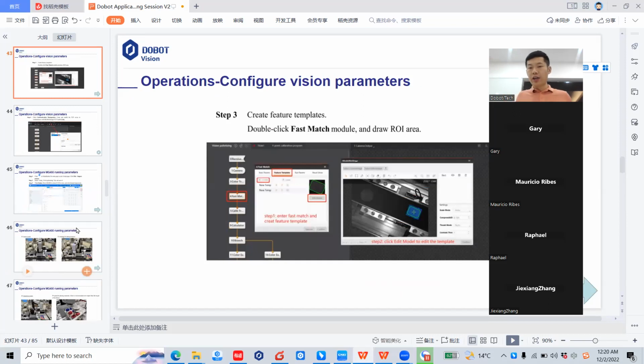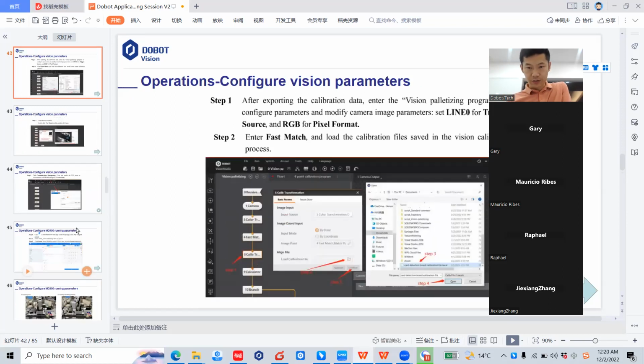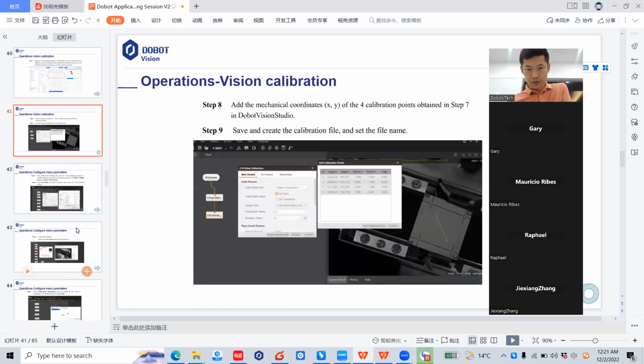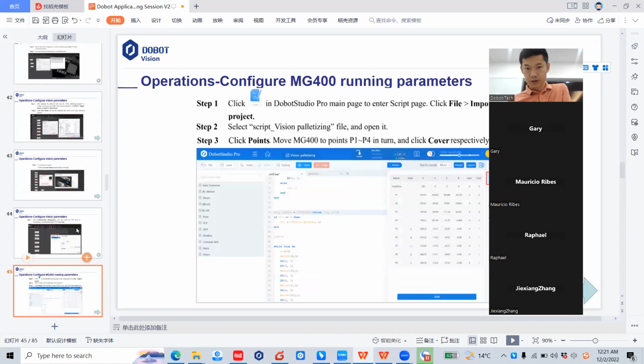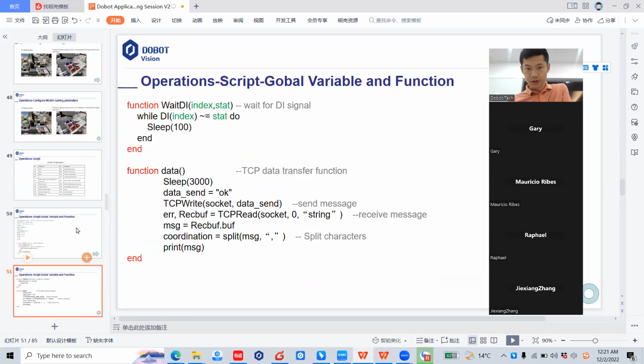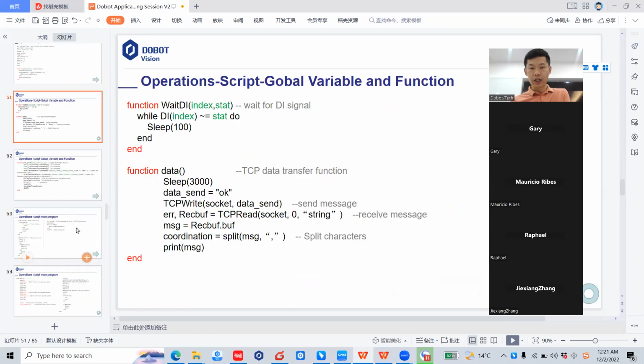Adjust on where? On the end effector, on the vision system? It would probably be on the height, the Z-axis. You would need to adjust lowering the arm plus or minus 5 millimeters. What do you mean by lowering the arm?